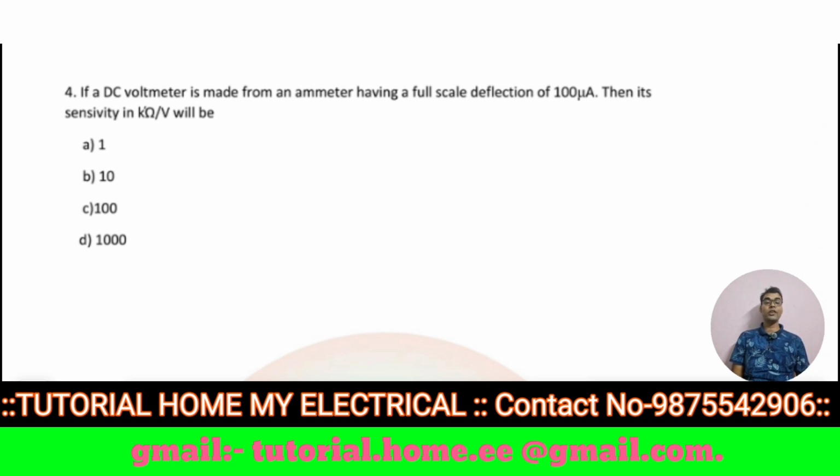We know the unit of sensitivity is ohm per volt, but in the question the sensitivity is asked in kilo ohm per volt, and the full scale deflection is given. So the IFSD, full scale deflection, is 100 microampere, which means 100 into 10 to the power minus 6. We know the sensitivity is the inverse of IFSD.